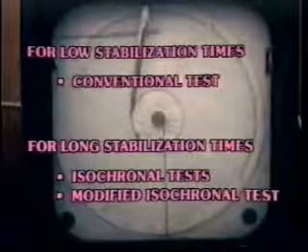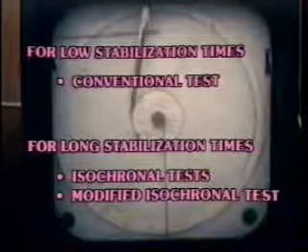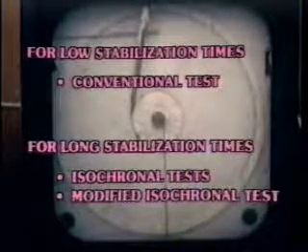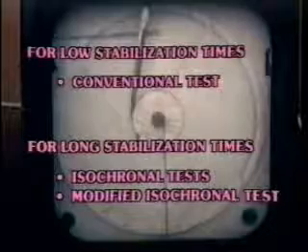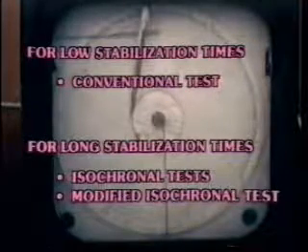In general, we can say that the time to stabilization will be long for a large reservoir with low permeability and short for a limited reservoir of high permeability. An estimate of stabilization time should be made before a test has begun. If a low stabilization time is expected, a conventional test may be run. But if stabilization time is expected to be long, isochronal or modified isochronal tests must be run. As we shall learn, state regulatory bodies often define rules of thumb estimates of stabilization time of the form less than 0.1% pressure drop in 15 minutes.